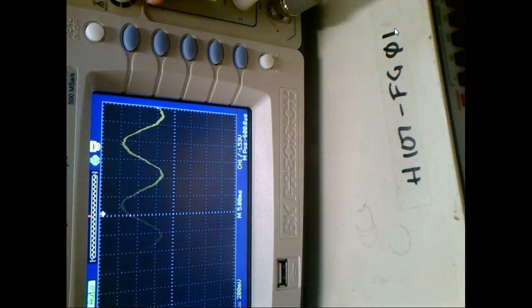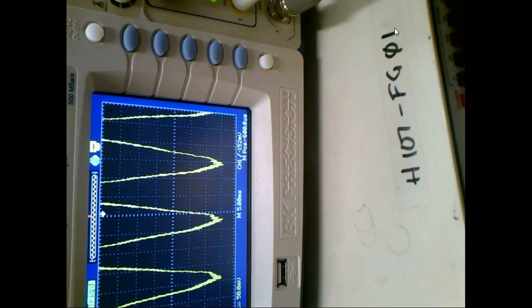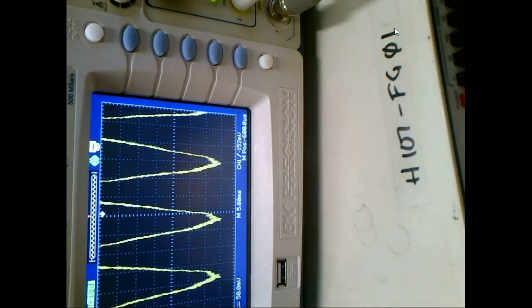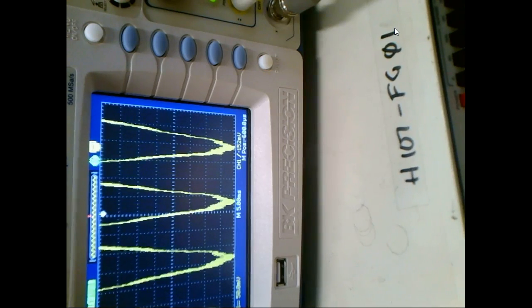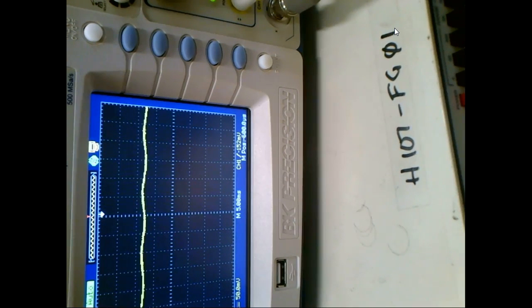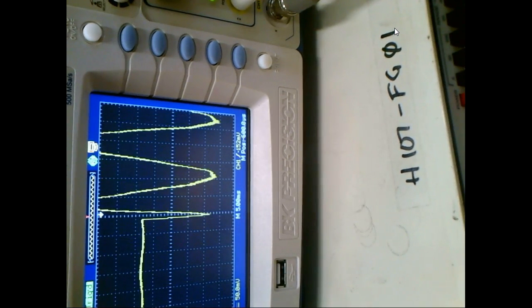And there's a lot of garbage riding on top of it because we've got all types of frequencies. That's the ghosting all over the place, because of all the other frequencies coming through the air. My body's picking them up. This is one way I check to see if my scope probe is hooked up and working, or if I've got the right channel selected. I just touch the tip.